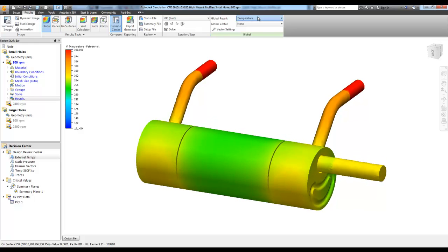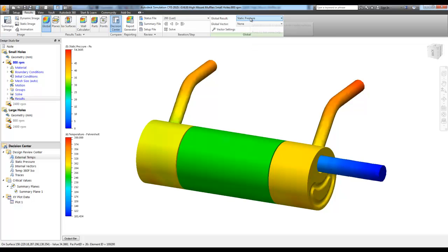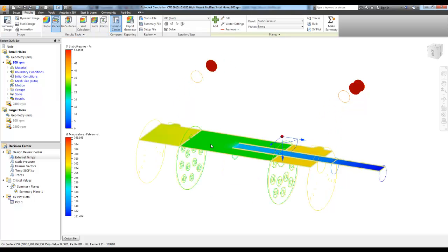Once we launch our CAD model directly into CFD, we can start looking at overall design parameters like internal temperatures and internal pressures within our design. Immediately with our first pass, we can start to see that we're seeing higher pressures on the cylinder on the right-hand side, which of course is our goal, is trying to get the best balance between the two.